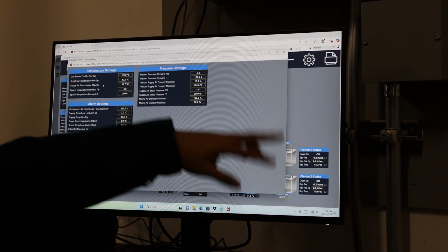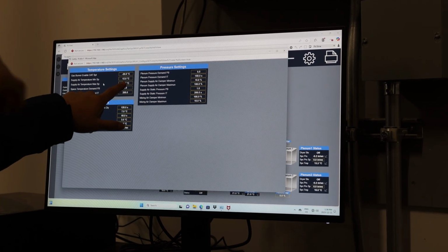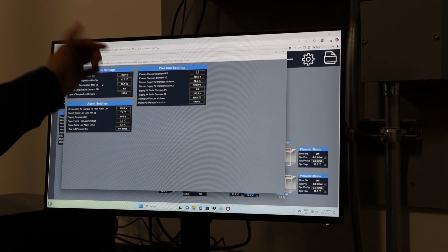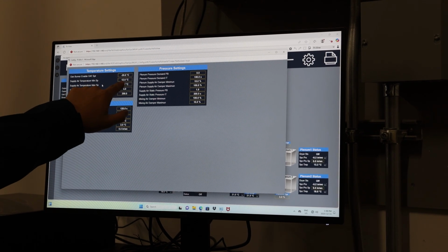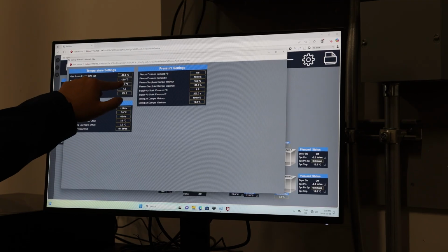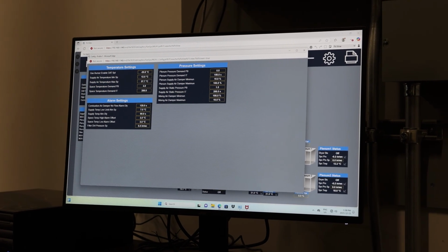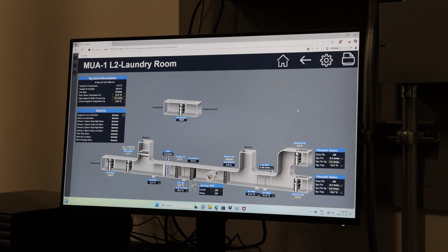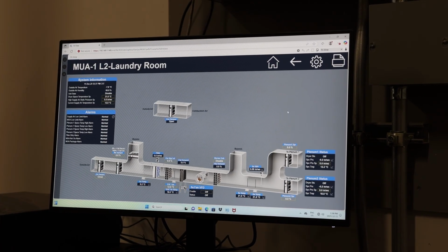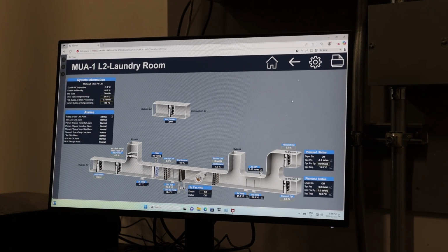If the space temperature is too hot, it goes down. Set point goes down. But it will not go to 12 degrees C. It also will not go to 37. For efficient operation, this is what I was told by the engineer, like the unit supplier.